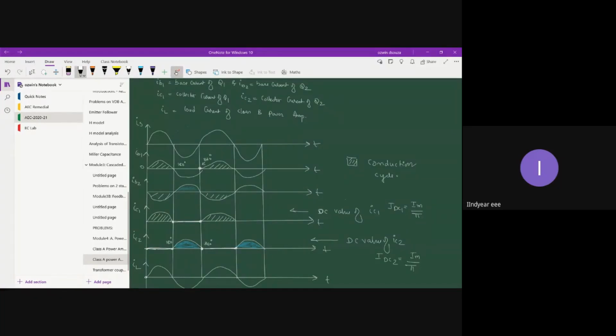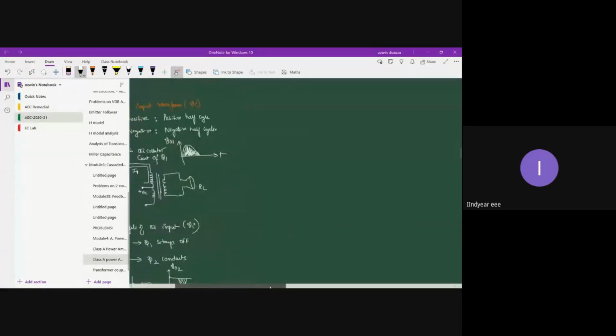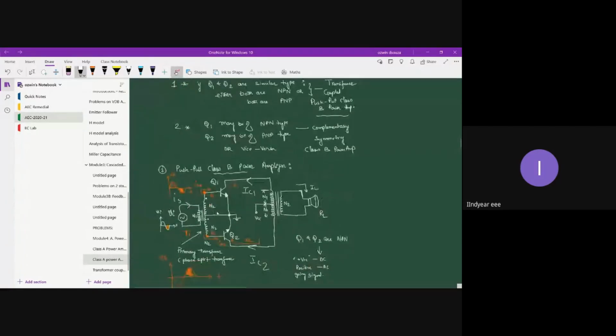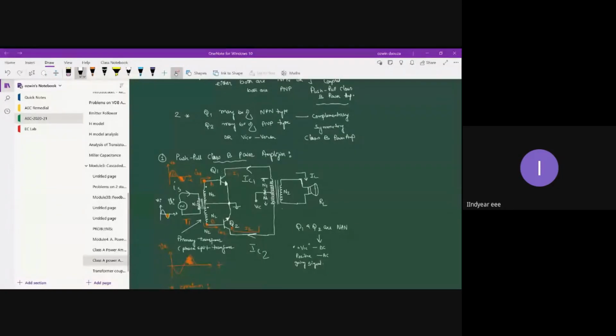The conduction is dictated by the primary transformer, which gives a phase-opposed secondary output: if the voltage at node A is positive going, the voltage at node B will be negative going. The NPN transistors conduct only for a positive going signal, so whenever there is a positive going signal, the transistor gets into conduction.